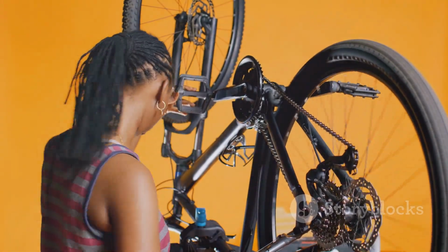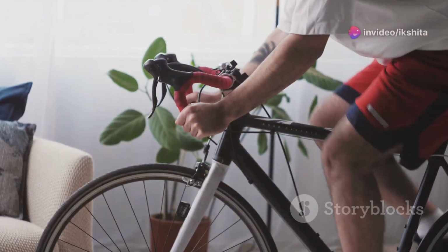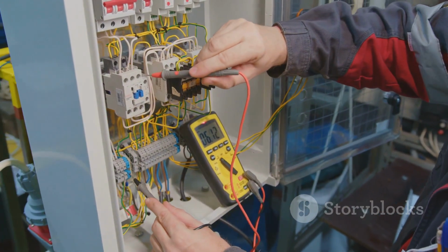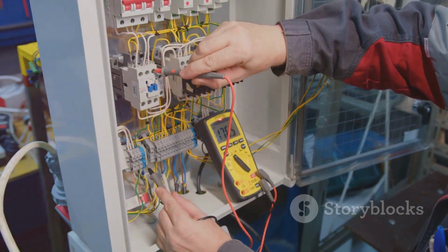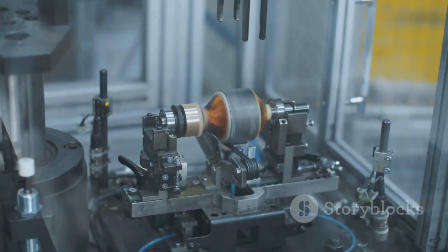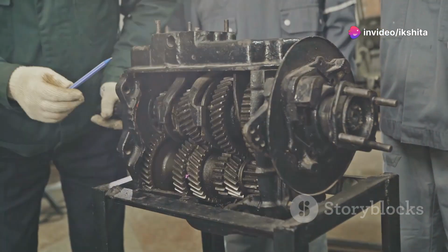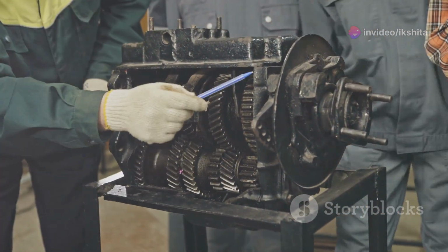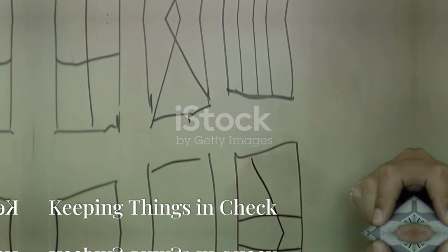Imagine a bicycle generator powering a light. As you pedal faster, the light should get brighter. But if the generator can't handle the increased load, the light might flicker or dim. That's poor voltage regulation, partly influenced by armature reaction. Similarly, a motor needs enough torque to start and run smoothly. If armature reaction weakens the magnetic field too much, the motor might struggle to start or operate efficiently.